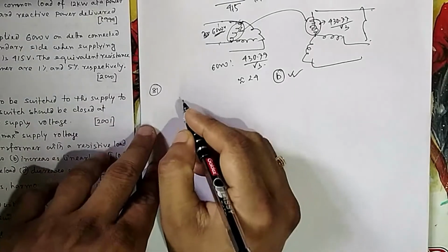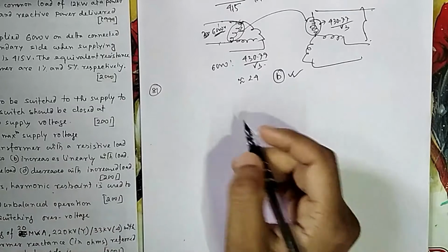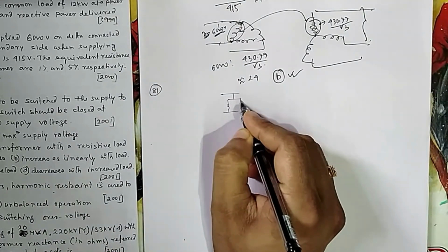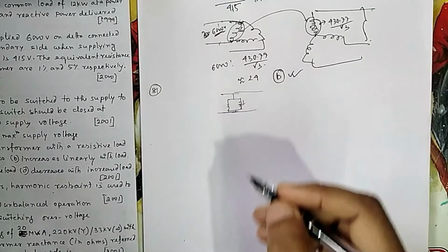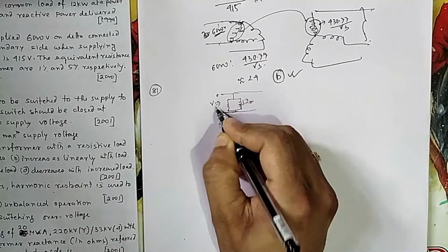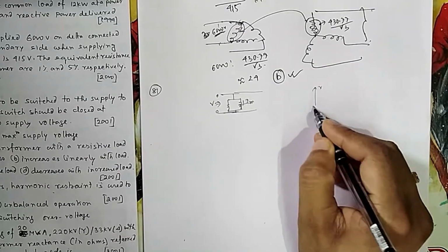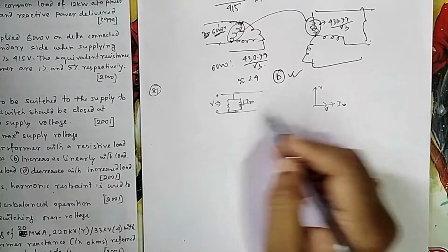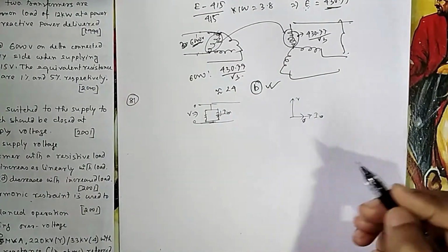Now, what is inrush current? It is magnetic inrush current, and how do we model it? In a transformer equivalent circuit, this is modeled as an inductor, because this is the magnetization current IM, which lags the supply voltage V. Whatever voltage you are giving, it lags this voltage. So if this is your V, then this is your IM. Actually this becomes your phi also, because due to that IM, phi is created. So this is always 90 degrees lagging.